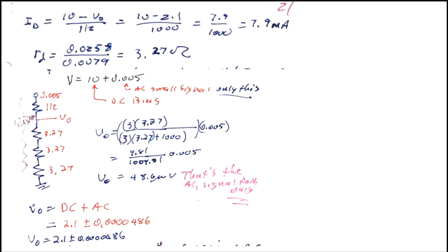And the nice thing is, it's really easy to work this and to understand it. The small signal model makes it much easier because we've linearized the circuit. It's much easier to understand what's happening. And it's actually a correct, true analysis. It gives us the right answer as long as that variation really is plus or minus 5 millivolts, as long as it is a small signal. And that's maybe a little bit big, but it's the right idea. I should change that to be 2 millivolts or something.